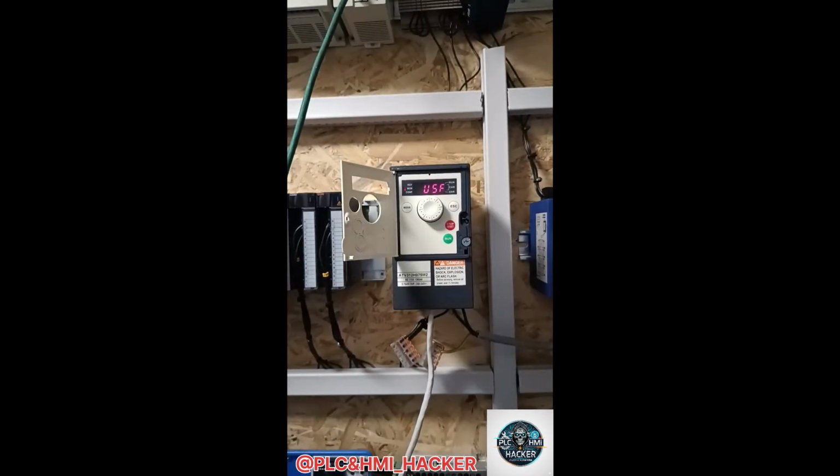Sometimes we get some error while doing the Modbus settings. I did get this USF error. In most cases it's enough to just cut the power and turn it on again to reset it. Else you can check the manual for the VFD to find more detailed fault information. When the VFD says NST, it is ready to run.